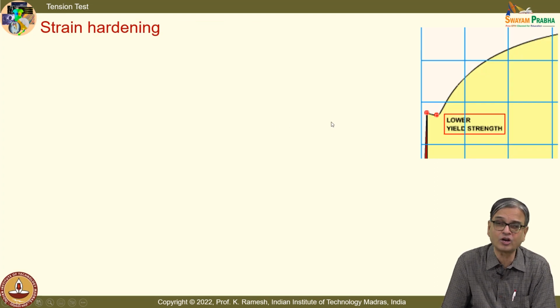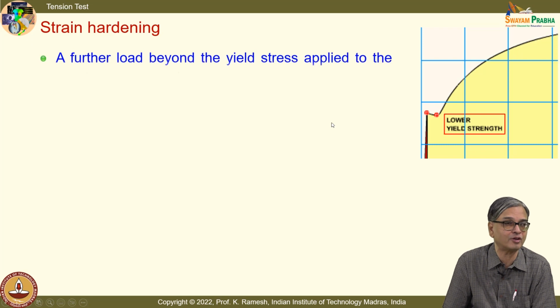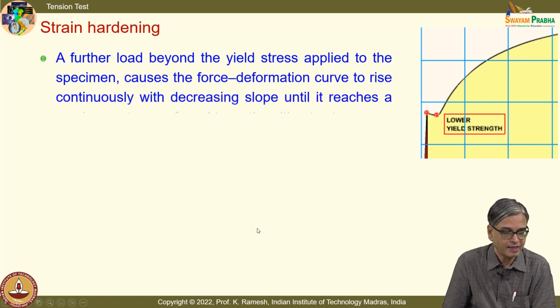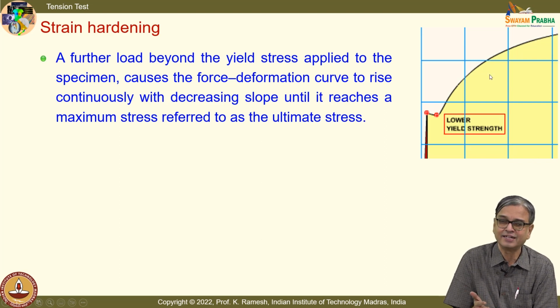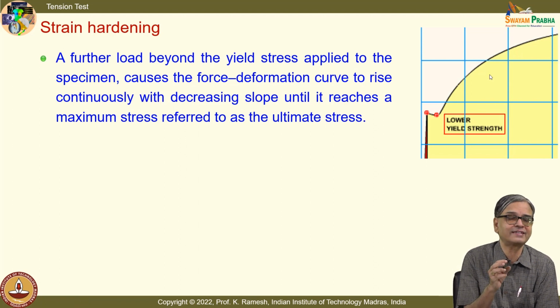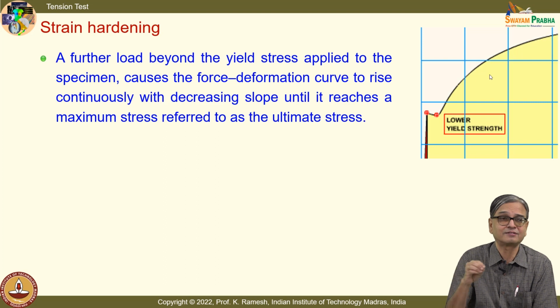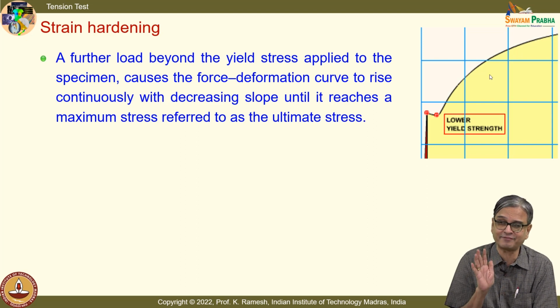See, scientists always want to coin new terminologies. Okay. So they have come out with a bombastic term like strain hardening, as if as the strain is increasing, the stress is also increasing. That is the meaning here. Fine. Because you want to escape. If suppose I want to model the complete curve, strength of material would not have developed. It is just because we have modeled only the linear portion, strength of material has developed.